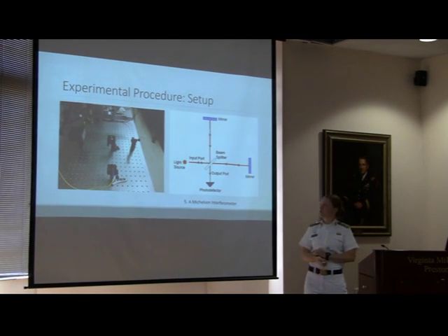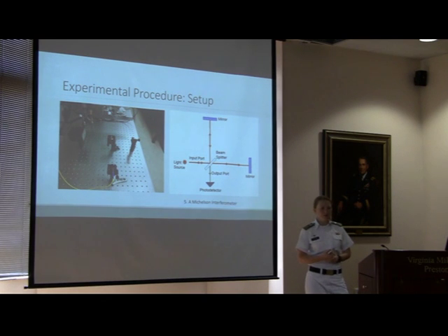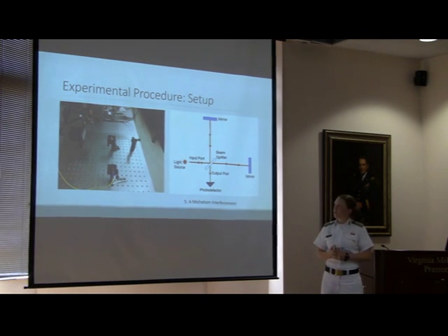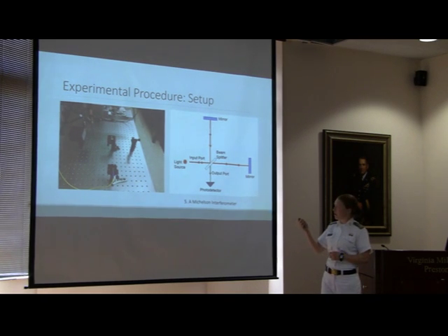Okay, so then that brings us to the actual experimental part of this. We originally set it up to be using laser Doppler vibrometry, but we realized that the amplitude of the vibrations wasn't high enough for that, so we used a simple Michelson interferometer, which if you've had optics, you should know about.